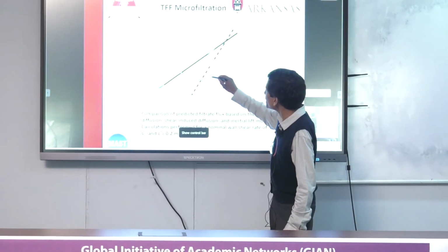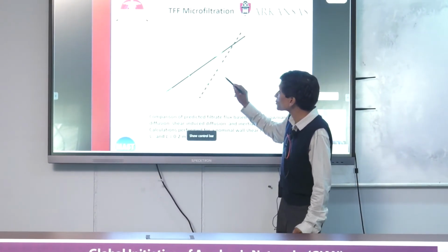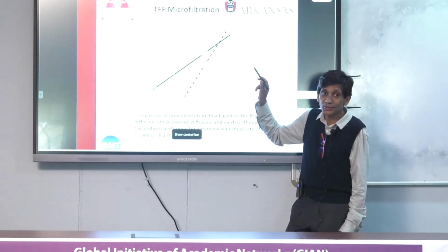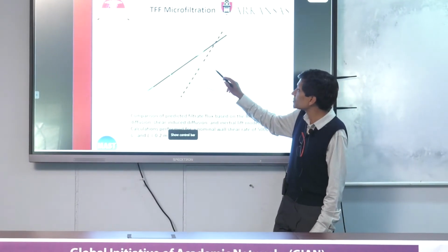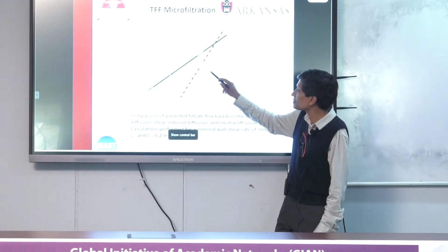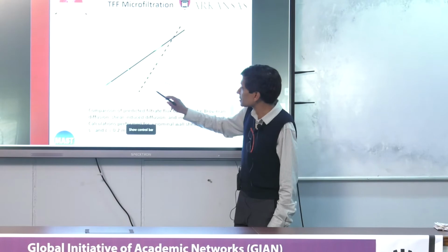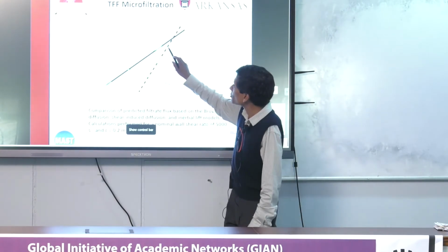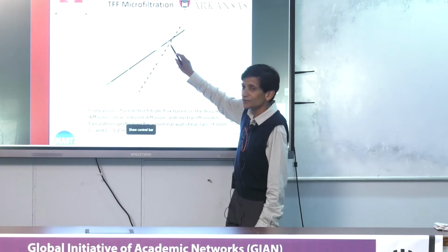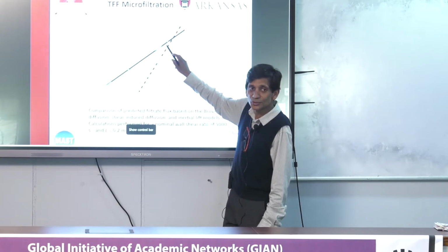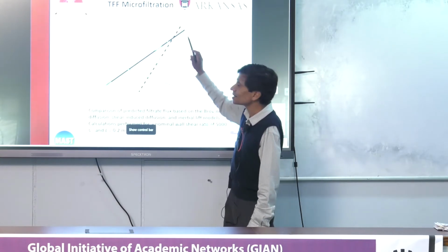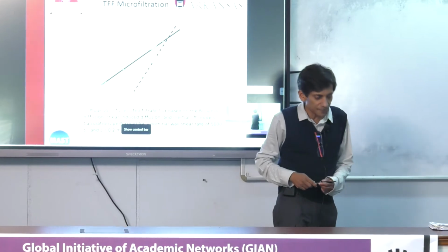If you look at inertial lift, you can see inertial lift actually doesn't depend on the length of the module at all, but it depends very strongly on wall shear rate and particle radius, so it increases rapidly. So what this means is if your particle radius is about 10 micron, you're probably getting equal contribution from shear-induced diffusion and inertial lift forces. For larger particles, inertial lift dominates.